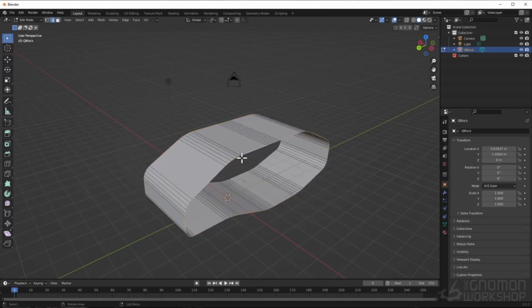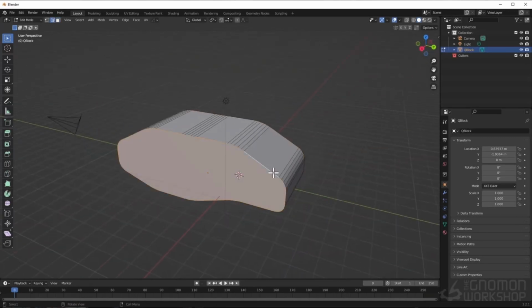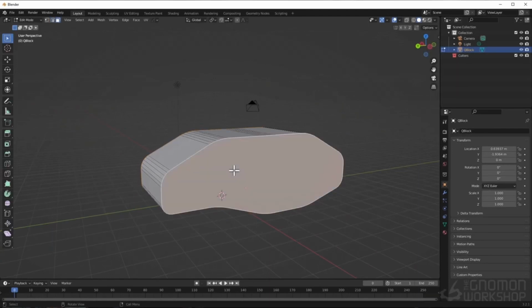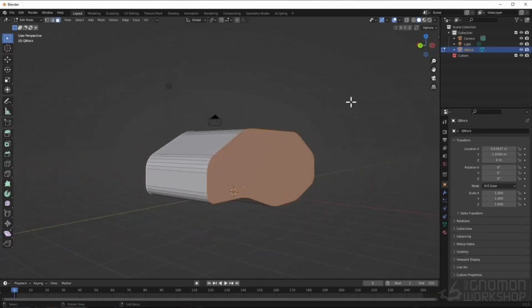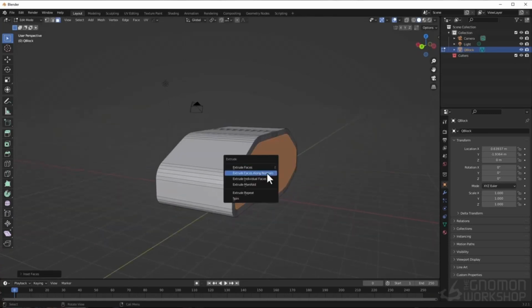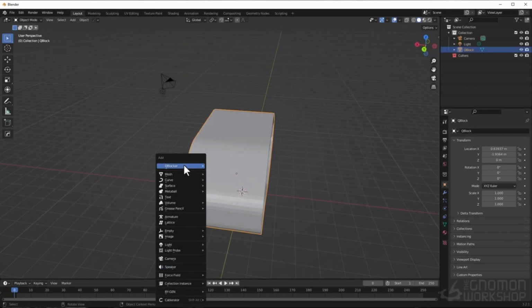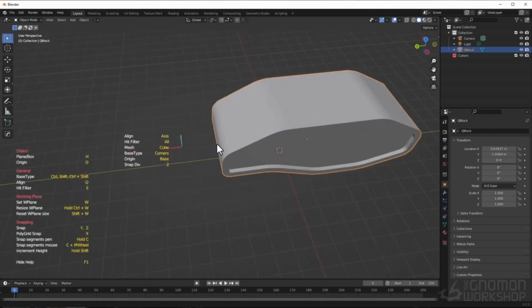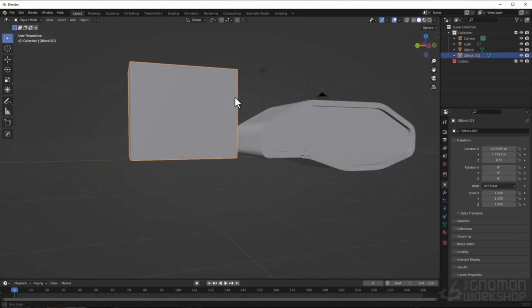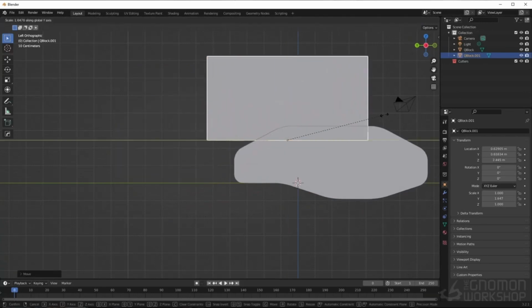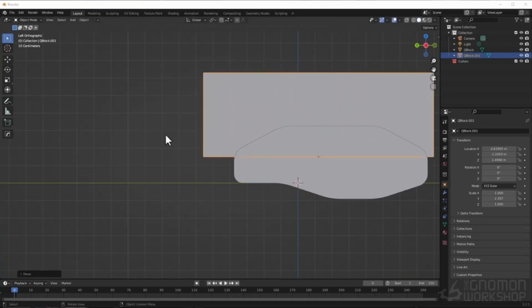Here, I'm removing the sides of this shape in order to simplify the geometry. I fill the open faces back in by selecting the edges and pressing F. I added a bit of detail to these sides by insetting with I and extruding along normal, which you can access by pressing Alt-E. I can then use QBlocker to create a new shape for the Boolean operation. I use this to get more complexity and to add details quickly. Just to note, I'm pressing Ctrl-A to get to the QBlocker menu.